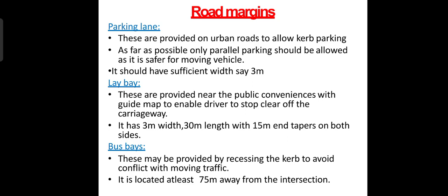Road margins. Parking lane. These are provided on urban roads to allow curb parking. As far as possible, only parallel parking should be allowed as it is safer for moving vehicles. It should be of sufficient width, say 3 meters.